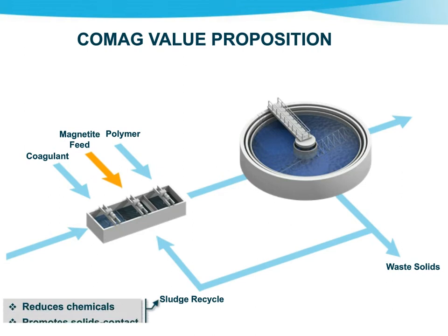To enhance the settling rate of the flocculated solids, a ballast media is added to the precipitated particles prior to the addition of the polymer. In this case, magnetite is used as a ballast media. The magnetite is added after the coagulant but before the polymer in the ballast media reaction tank.